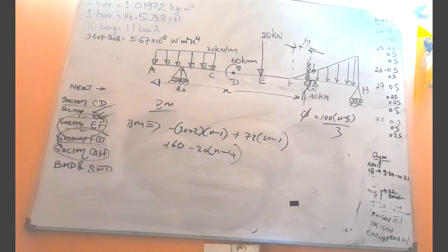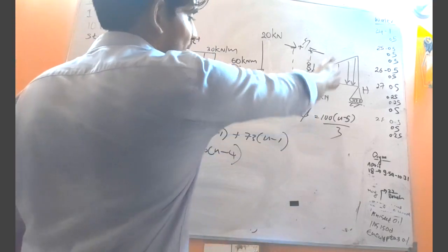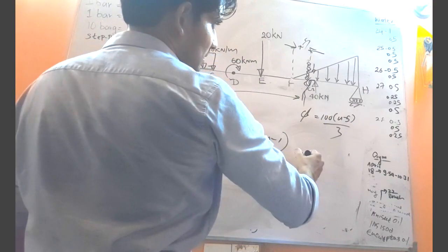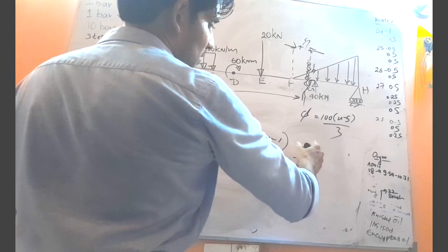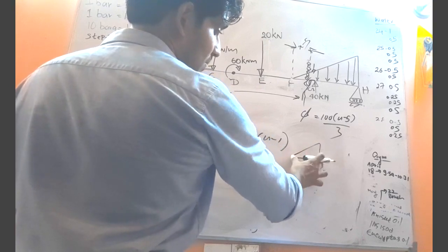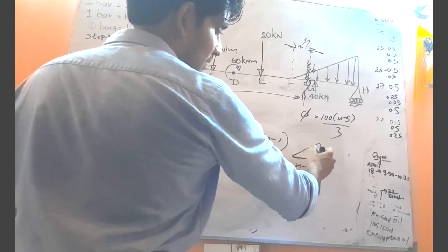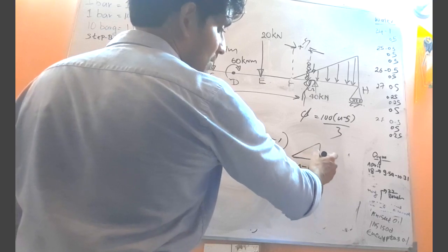and then, what is the center of gravity from here to here? Now we know the base length is x minus 5. The center of gravity will be at 2/3 of the base length, so the length from here to here will be 1/3 of the base length.